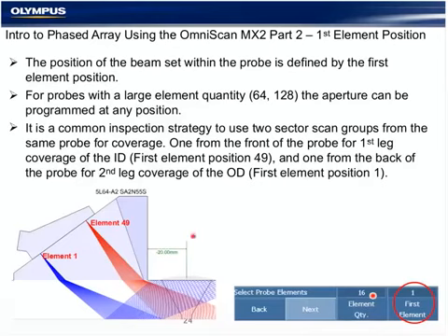In this case, this probe has a 0.6 millimeter pitch. So if I use 16 elements times 0.6 millimeters, that is going to give me a probe aperture just short of 10 millimeters. The two parameters I'm seeing here are simulating a 10 millimeter by 7 millimeter conventional beam. And we can manipulate it with a beam tool plotter like you see here, or directly in the instrument.